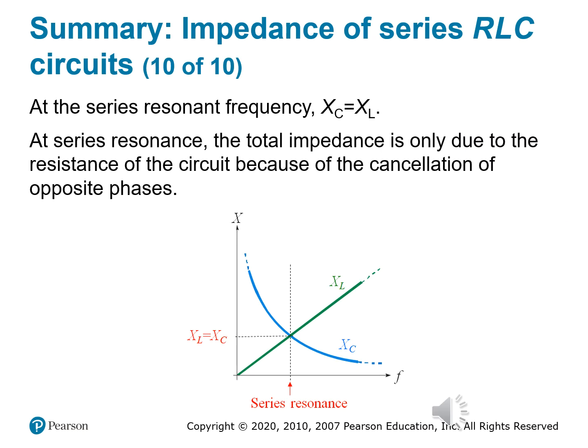And you can see that moment on the graph, right? At the intersection of X sub C and X sub L in the curves. That's your resonant frequency, where the imaginary part of impedance vanishes and your circuit behaves like a simple resistor. Again, why does this matter? Because at resonance, current is maximized. So we know a special condition at this particular frequency. It's the most efficient condition for energy transfer. Your voltages are still oscillating, but the energy tug of war between L and C is perfectly balanced. Think of it like the universe snapping into harmony. For just one brief, beautiful moment, everything just clicks.